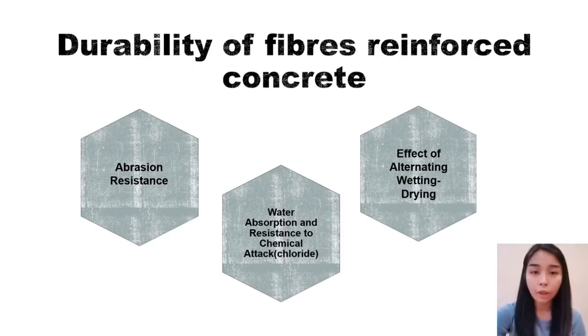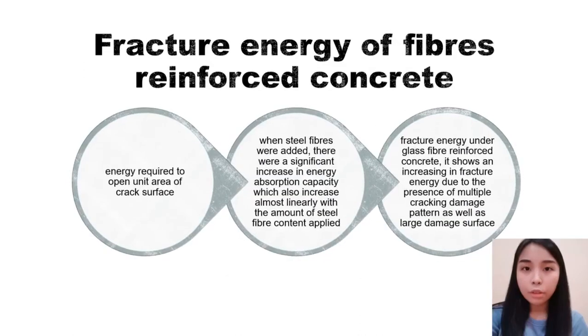Third, the effect of alternating wetting and drying. The degradation of concrete was minor in the case of high-content slabs of steel fiber reinforced concrete under wetting and drying conditions. Fracture energy can be defined as the energy required to open a unit area of crack surface.